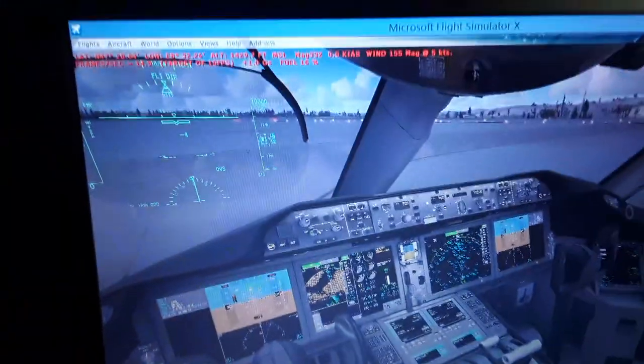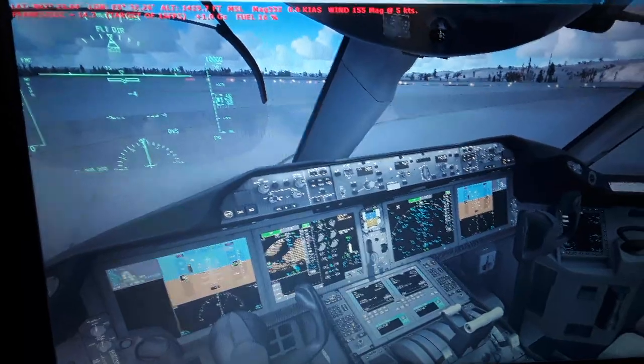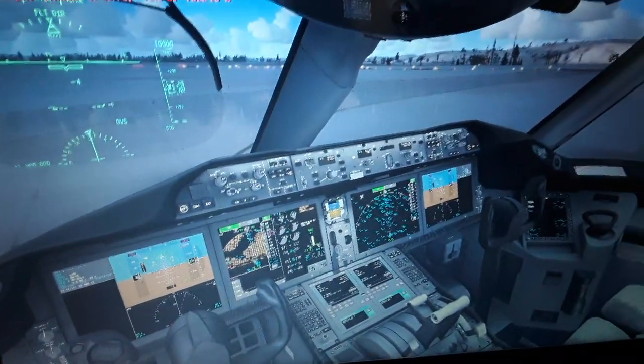We have also the radio altitude above ground level that can display up to 2,500 feet, and the horizontal situation indicator. We can see the magnetic heading and track, and also the integrated flight plan display. You can see the purple magenta lines of the flight plan. So we have the waypoints and the STARs. We can enter and select the waypoints from the flight management computer.